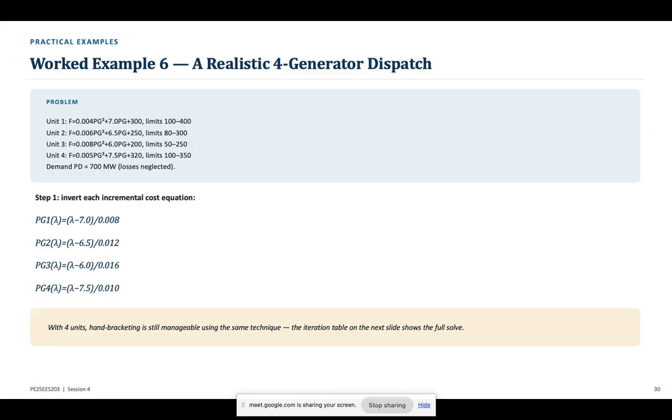Why? Because incremental cost means you have a cost for the generation for a certain load. If you increase beyond that, there is extra cost which gets added. If losses are considered, losses will also get included. That we call a penalty factor. When Lagrange comes in, then we have a penalty factor. Those are the few things we discussed in yesterday's class with the numericals also. You can go back and refer to the recording.